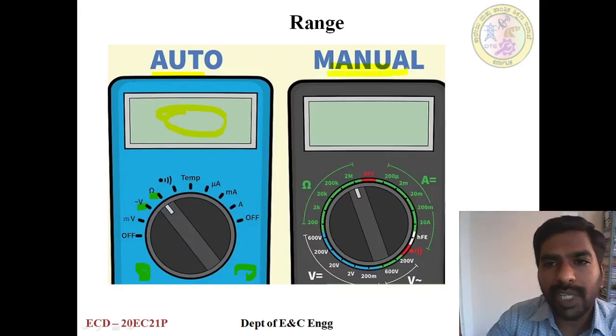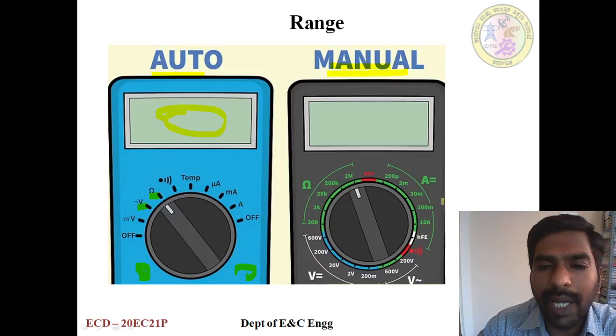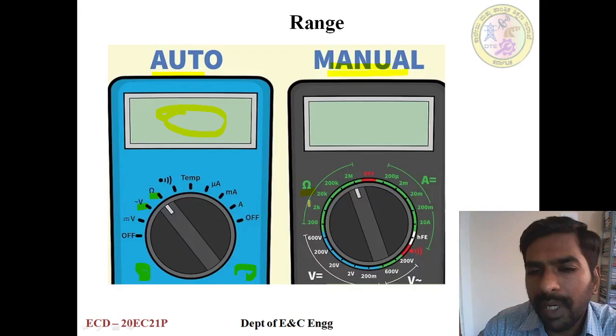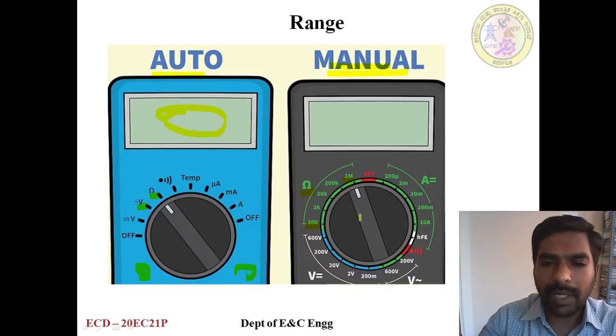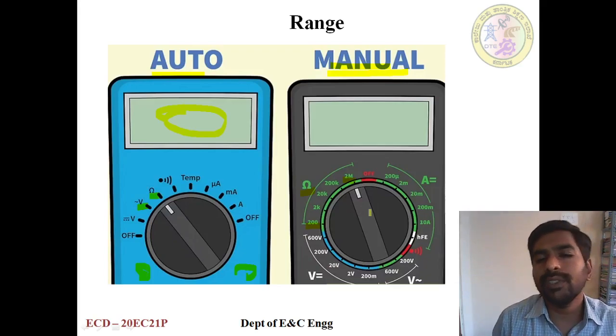But for manual selection, the low-end multimeters that don't have auto select have to use the manual range selector. See here, if you select ohmmeter, the range varies from 200 to 2M. Users of the multimeter have to change this range knob as per the device value.